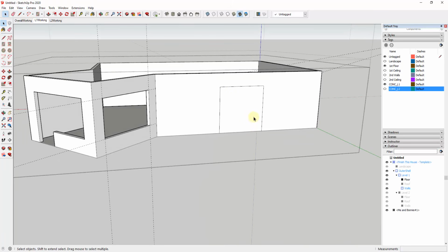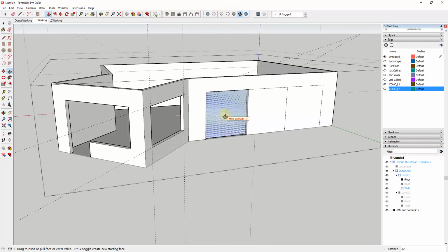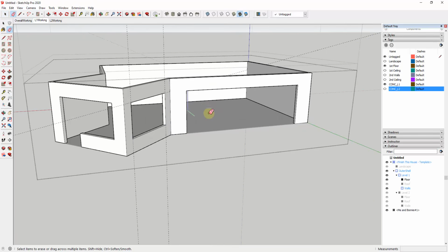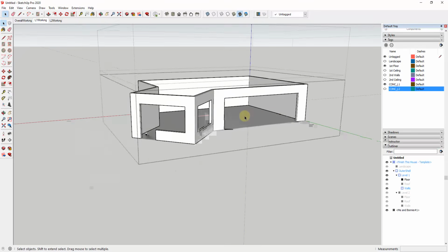So this is going to be the opening for the door itself, and then I'm assuming that we're going to have some more full height windows over here as well. So we're going to say this is going to extend another 7 feet this way, and 7 feet this way. So we're going to go ahead and cut the opening for this glass in here as well. So you can see how all I'm doing is just cutting out the openings for my windows right now. And so now let's say that we were going to come in here and model out these windows. You can either erase these guides or not, depending on what you're trying to do. That's kind of up to you. But for me, I'm going to erase them out just to keep everything kind of clean.